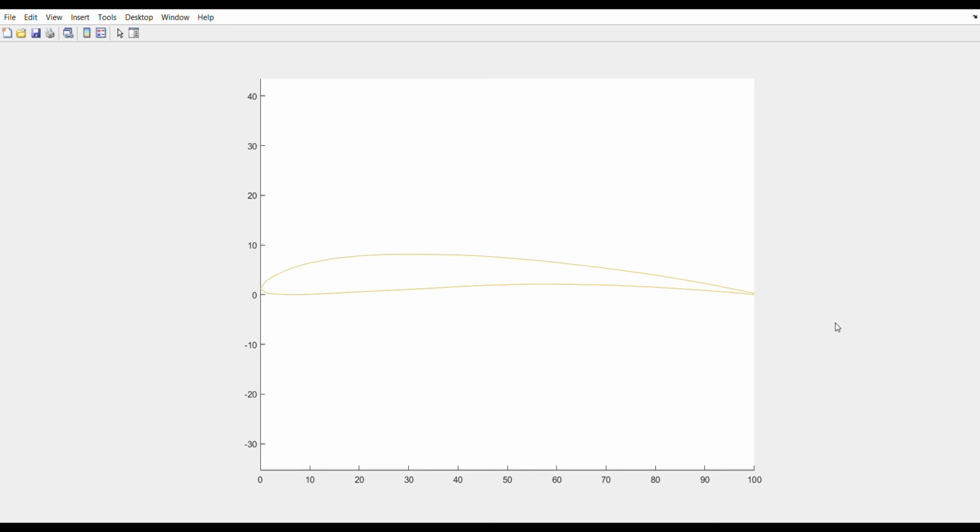And basically what I did is I saved this as a JPEG file, and I found that in SolidWorks you can open up a sketch and insert an image onto a sketch plane. So I inserted this image onto that sketch plane and then traced out a decent area around this airfoil that we want, trying to exclude any of the axes.